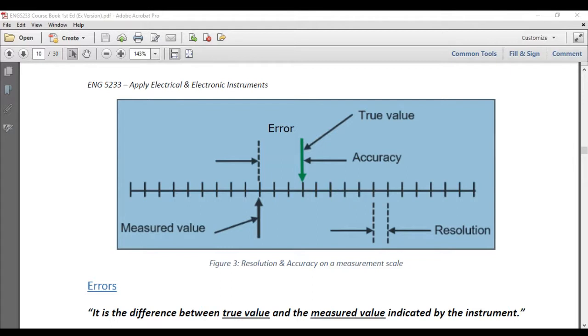You have two voltmeters, and one can measure with a division of 0.5 volts. So if from 0 you increase the voltage, then when you are increasing the knob, the next reading after 0 will show 0.5 volt. You increase the voltage again, it will not show you any reading between 0.5 and 1.